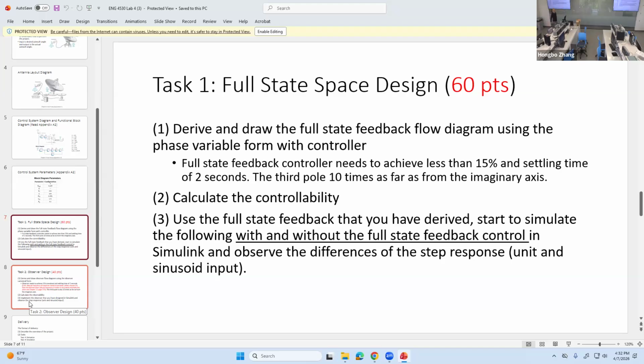All righty. So you better do the controllability calculation first before wasting time. And within task 1, I ask you to do another thing: calculating the pole placement gains. You say, I want to control this radar, so what's the pole placement, and what's the gain I need to control it? This is the idea of pole placement, and calculate the K.